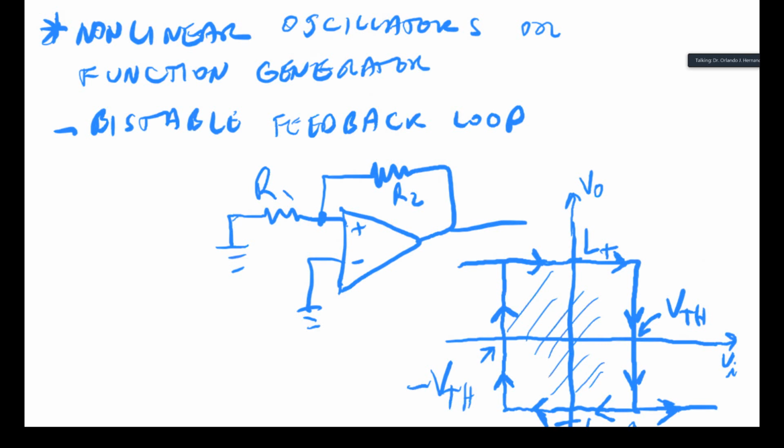That this op amp with that feedback in the positive configuration has. So we can take advantage of that behavior by using it. And what we can do is use that as an amplifier and then set the timing with the beta network. So what we could do is now get rid of this ground point here, and we can set timing by using an RC network.